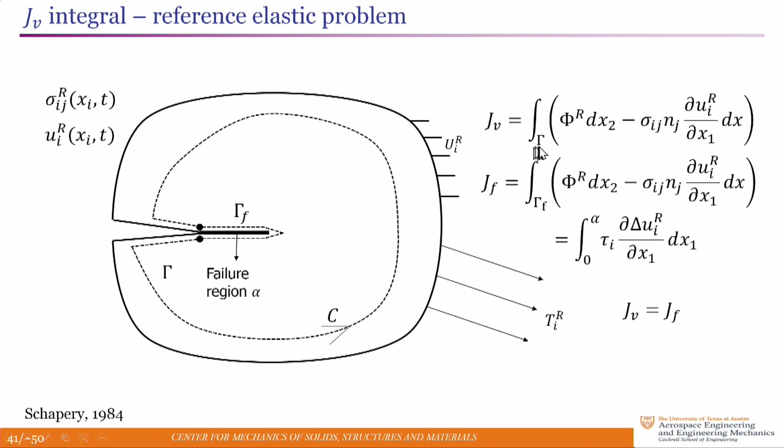And the two are equal. So if you measure far field displacement and strain quantities, you can calculate what happens in the fracture process zone, and that's the thing we use to characterize the connection between the applied load, represented only by this far field elastic integral, and the local dissipation, represented as the work of fracture. We extract that in terms of the measurement from the far field.